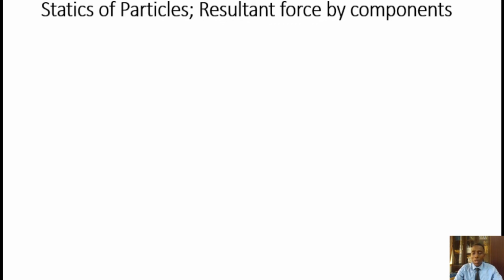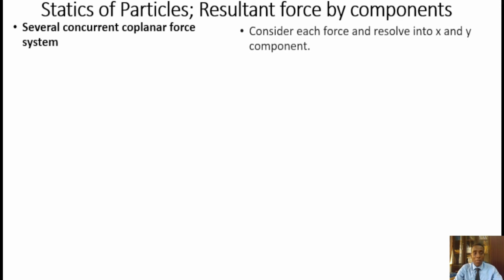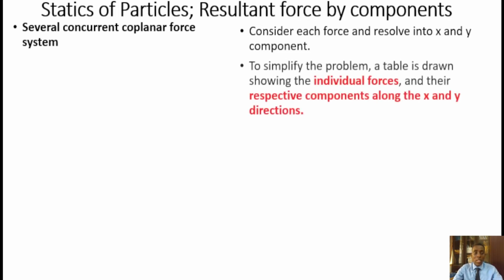So in this video, I want to teach you, or explain to you, how to resolve forces which are concurrent and coplanar, several of them. So, a concurrent coplanar force system. What do we do? Consider each force and resolve it into x and y components.